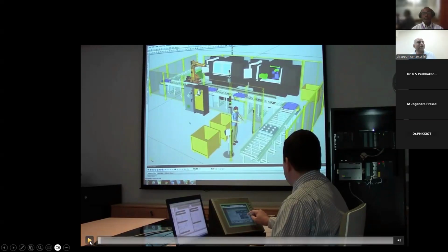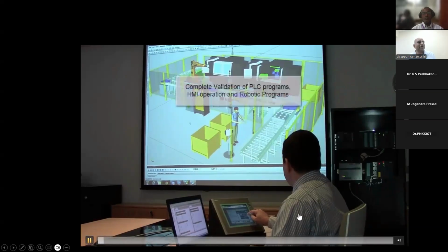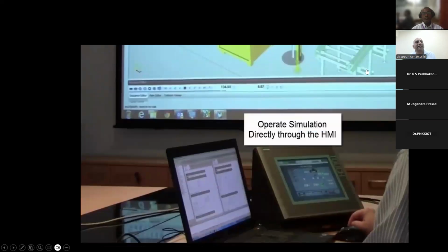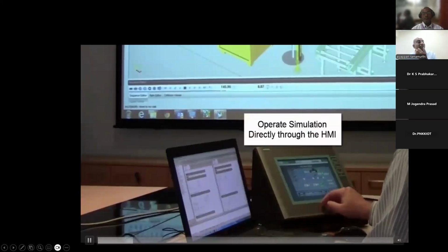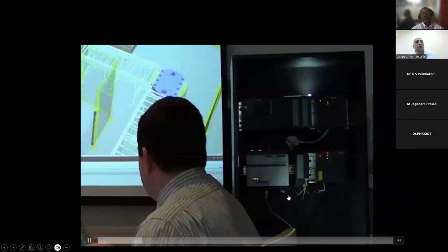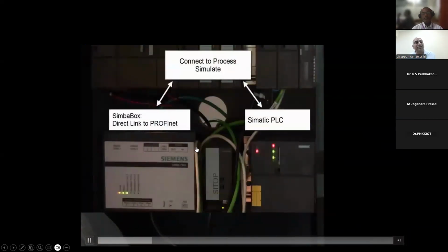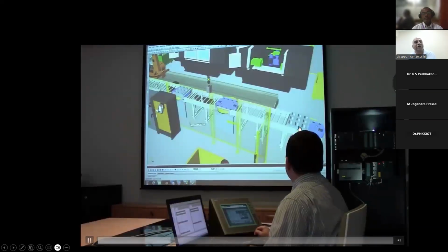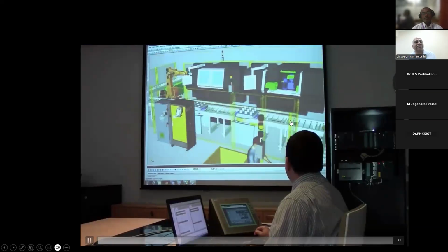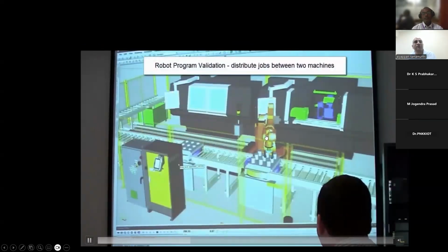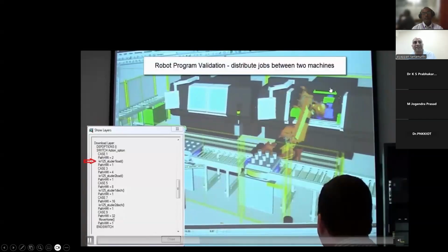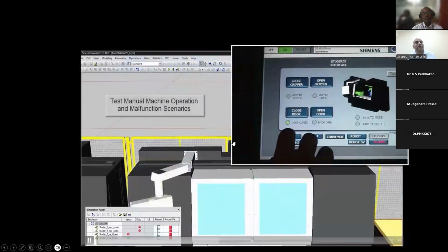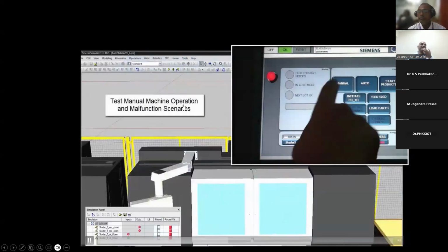So you can completely build the twin sitting in your college, in your labs, to create a production system. You can do the line design, create these conveyors and CNC machines and all that, and also create PLC programs. The PLC programs, the ladder logic controlling the production, show how well the conveyors behave, passing through the signals, getting the information, so that the robot can come, pick and place, and here maybe a machining happens. And there is a cycle time which it takes, and use the same robot to place for the second machine as well.